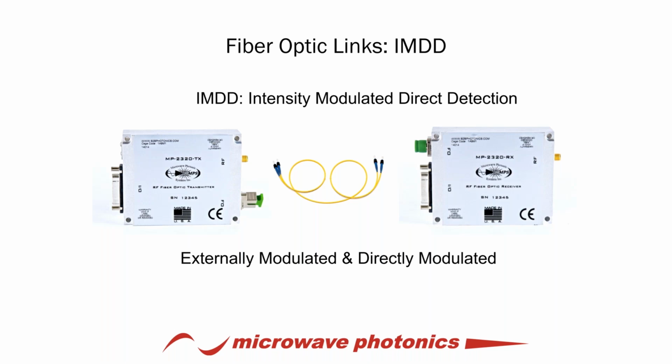That is, the laser is modulated, varied in optical signal intensity, thereby imposing the analog signal on the optical carrier. And the process of doing this presents a format agnostic neutral host transport methodology, which doesn't put encryption. There's not an analog to digital converter.